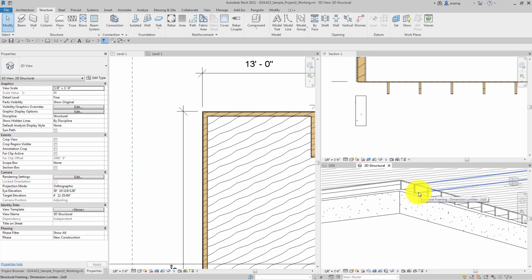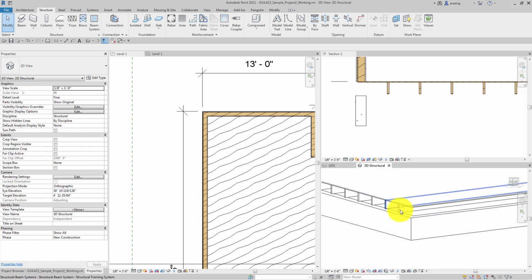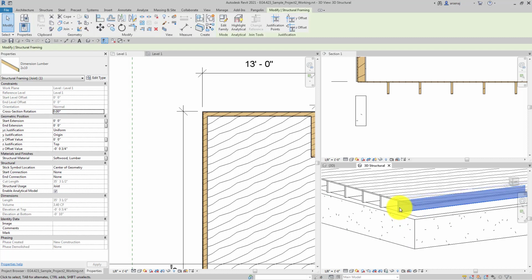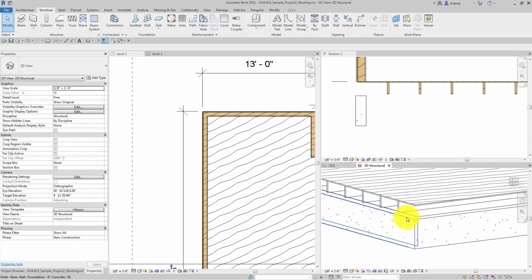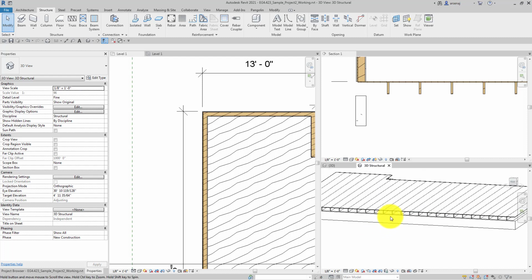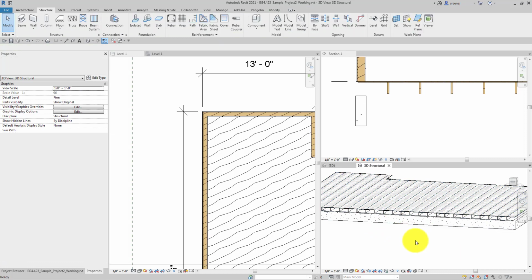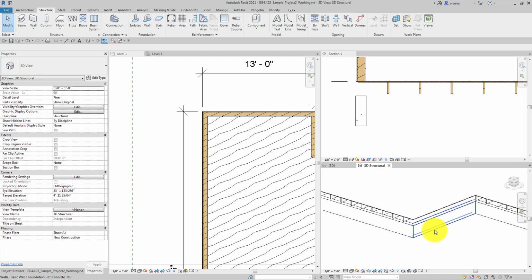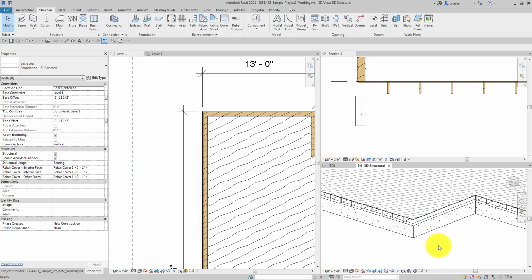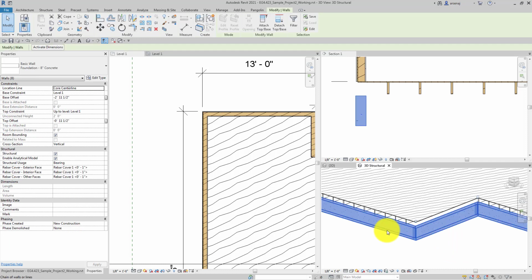Because in Revit, beams and walls and columns, they want to connect to something. They'll auto join. So if when you place your wall, it was initially in this joist space, it could cause your joists to be set back to the face of this wall. And it can be hard to disallow the join because we're using a beam system. So if it does that, you'll want to delete the wall. You can just hover over it, tab, delete it, and then try to replace it again with the correct offsets.